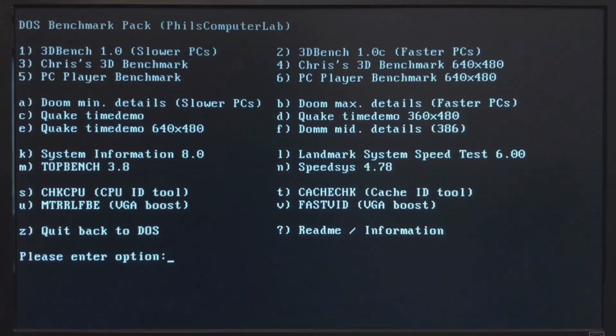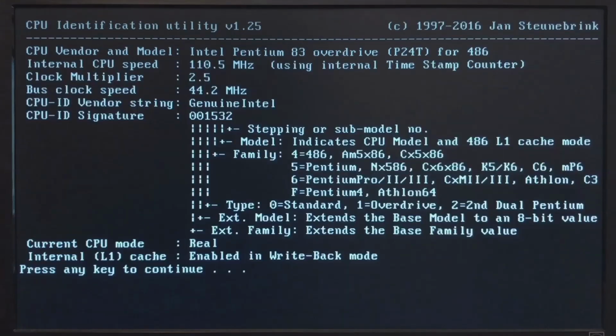So the time has come, and this is what I finally got. I managed to overclock to 110 MHz with a bus of 44.2. I'm quite pleased with this result. The CPU before the mods could not even do 100 stable, even with some extra voltage. By the way, even when I used just the small heatsink with a fan, I was able to do 106 MHz. Both configurations were completely stable. Now, in order to go above 110, maybe I need a better CPU. I was again very unlucky with the CPU lottery.